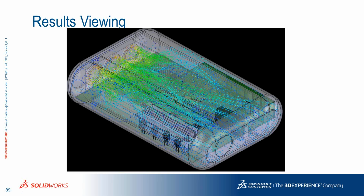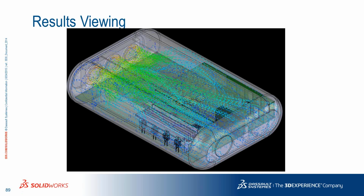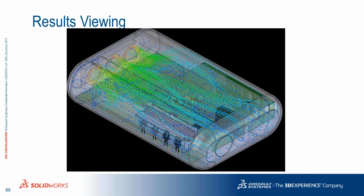And right off the bat, when you look at this flow trajectory animation, which is 3-dimensional in space, you get an idea of what is going on, where the gray spots are, where the stagnation areas are, whether air is trying to recirculate or just be stagnant in certain areas of the design. Am I getting sufficient air circulation around critical parts of the assembly, for example, IC chips, RAM chips? That's the kind of visual feedback that you get right off the bat by simply looking at a quick animation of the flow trajectories.